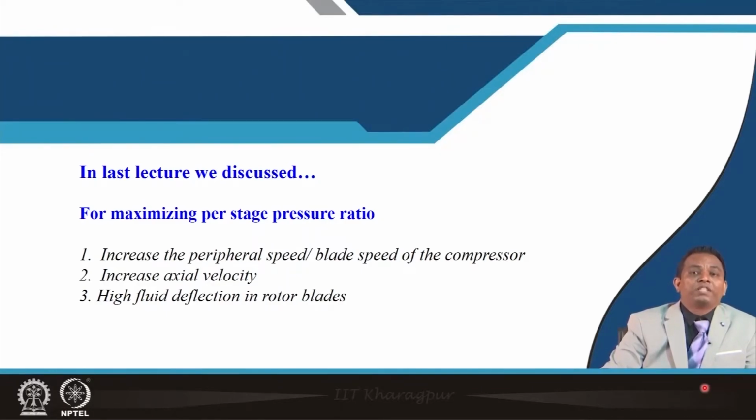For the first two cases, we have observed that increasing the peripheral speed or the axial velocity leads to shock formation near the tip region. That will lead to increased losses and blockage to the flow, which will reduce the efficiency.